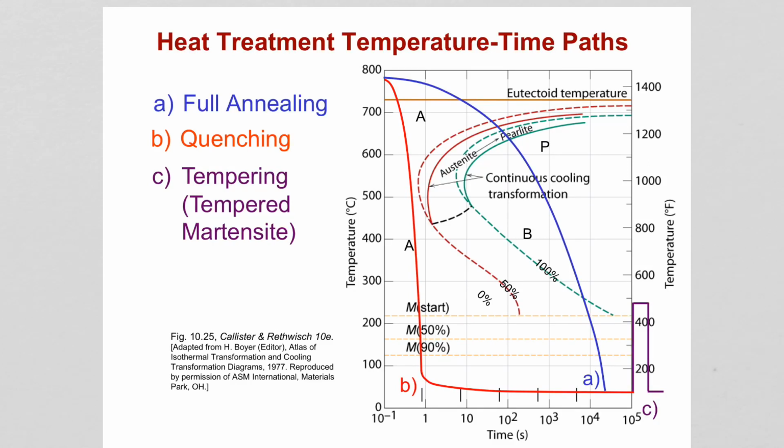We are seeing the continuous cooling transformation curves here and the cooling curves. As you can see, the red one is quenching. Remember, when we do quenching, when we start at a temperature above eutectoid and we quench it immediately, austenite goes to martensite, as you can see here. Okay, and then it is full martensite at room temperature, and if you keep it at room temperature, it is now martensite. And what you can do is tempering and transform some of those.